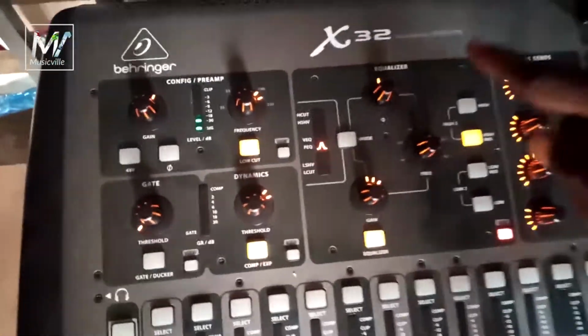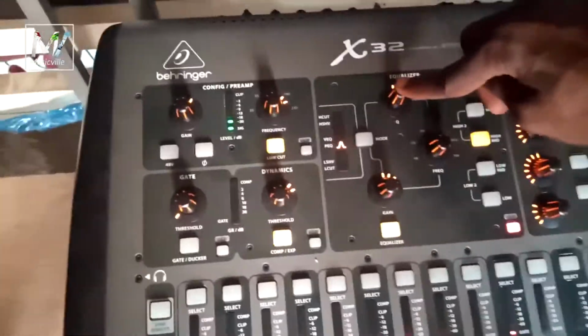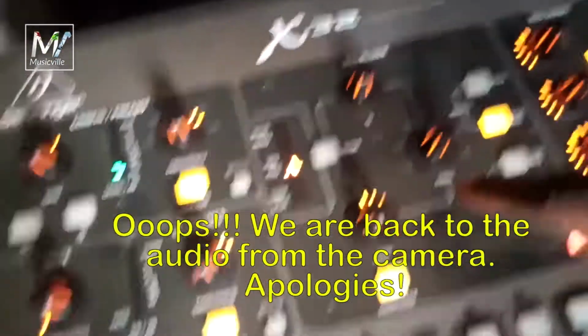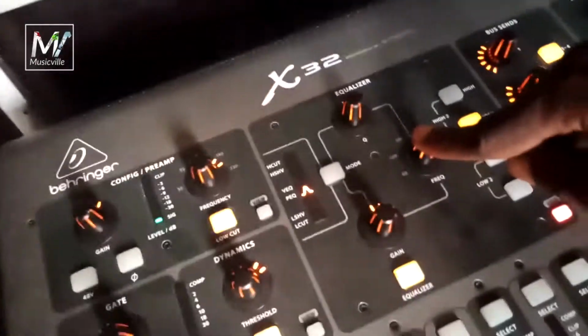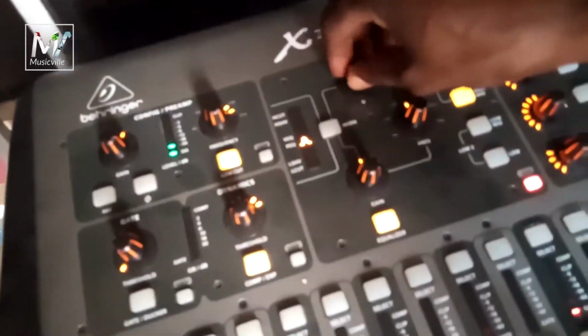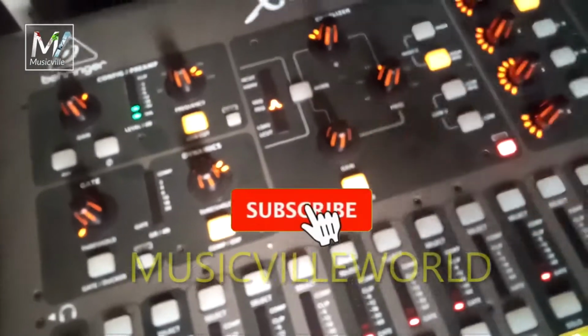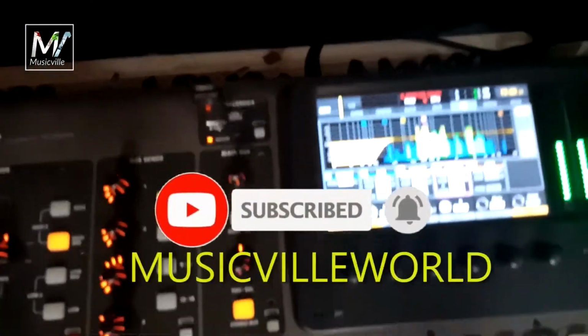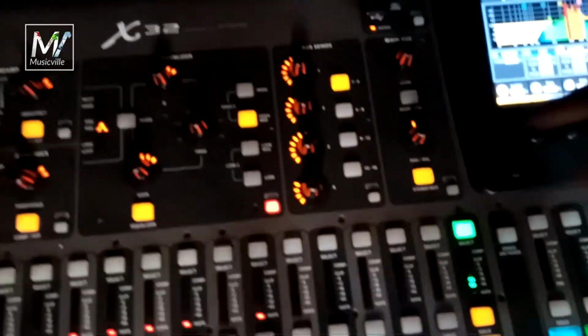Now, if I'm able to determine the width of whatever I want to cut down with my Q factor, then I'm able to determine the frequency or sweep around where I want to cut. Then this gain determines how many decibels, or how much volume, I'm to reduce or increase.